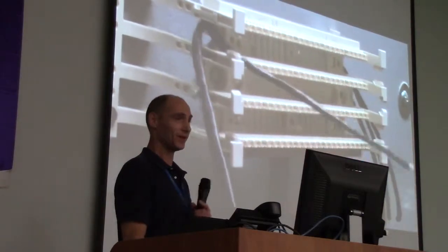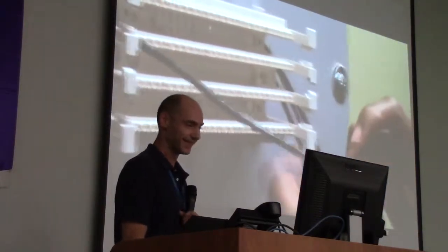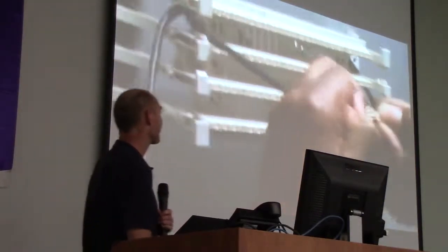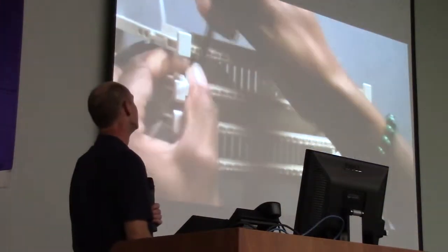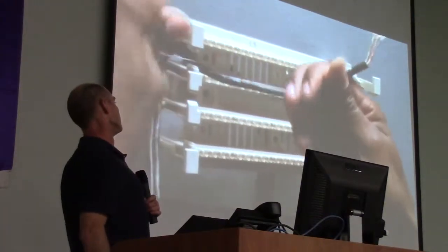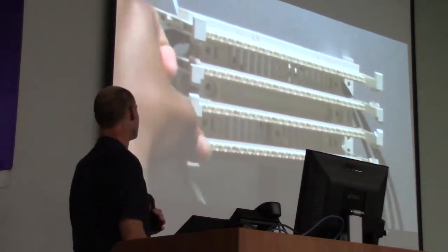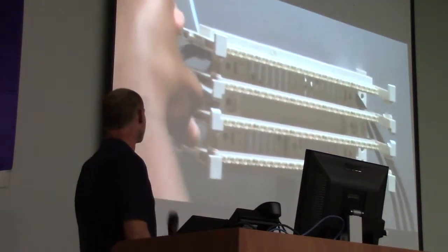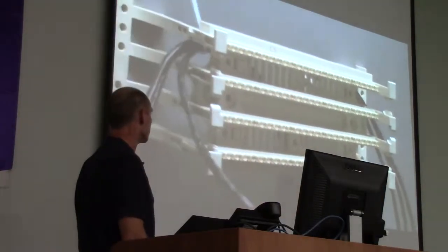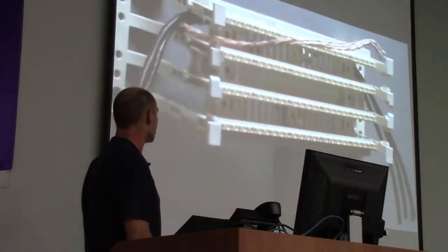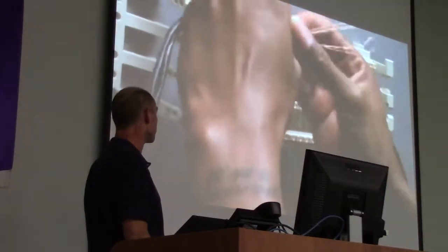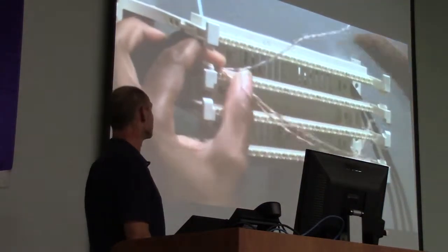Alright, as you can see, I stripped the cable back so I can use the pull string to pull that cable to the right length that I want to terminate at. I'm going to do that. Take the snips here, cut this pull string and cut that existing jacket off. And you're going to go with 568B today.